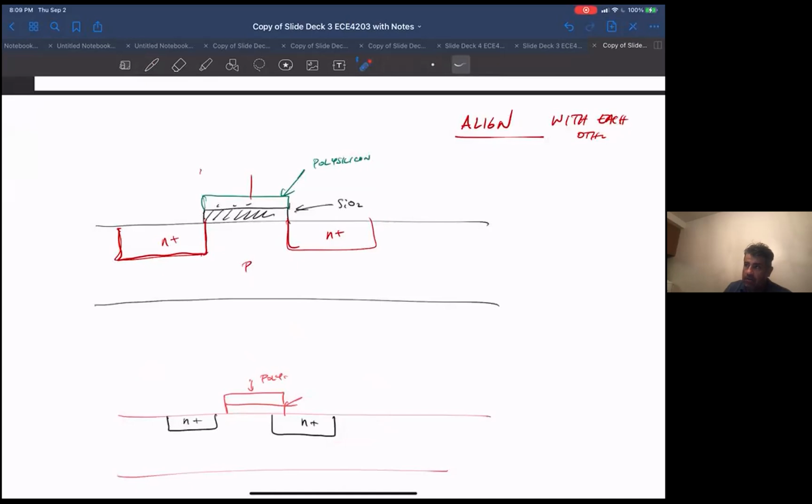And you can imagine every layer is like that. If I was going to put a piece of metal here, you could easily end up in a situation where the piece of metal would end up here. Remember, these are 3 nanometer, 5 nanometer, even big ones are 65 nanometer features that you're printing. So these various masks or steps have to be really super well aligned with each other. And there's still some misalignment.